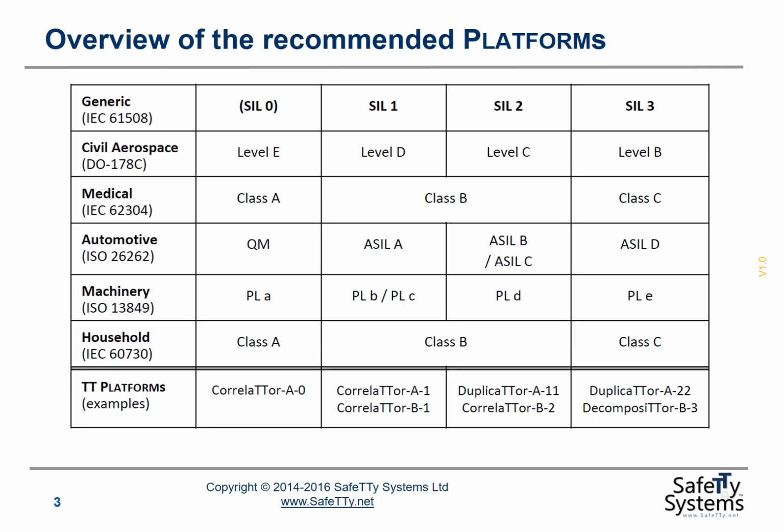The platforms that we present are designed to cover a range of different safety integrity levels. So if we start by viewing these from the perspective of IEC 61508, the generic international safety standard, we'll be looking at a range of platforms in this video that cover systems from SIL 0, which are not safety related, up to SIL 3, which are a high level of safety related system. This is not the highest level that we get to in IEC 61508, but it's the highest level that's commonly used in the majority of systems.